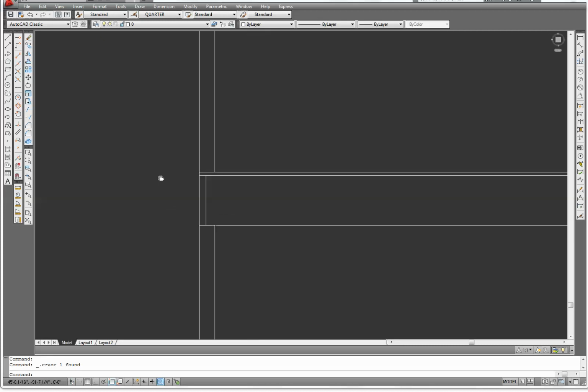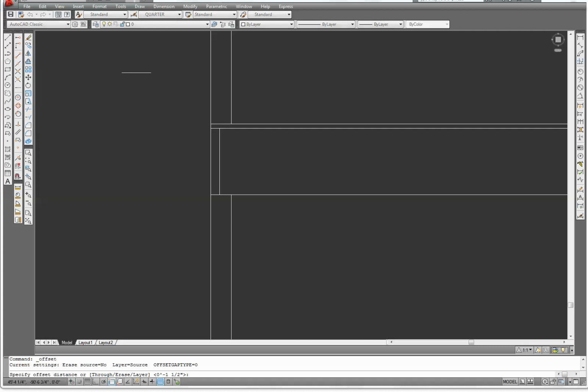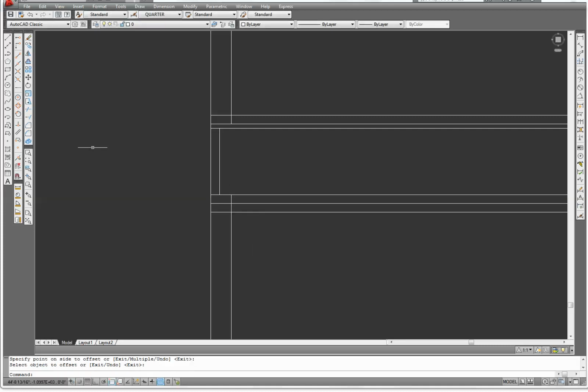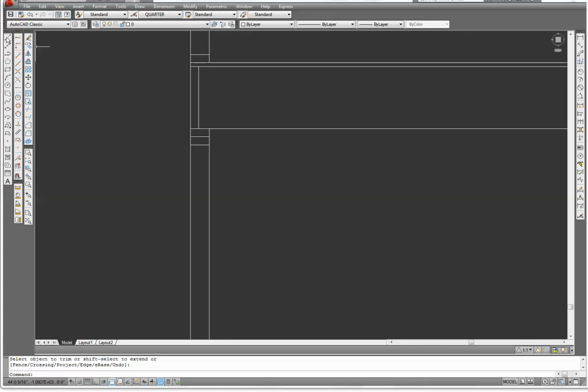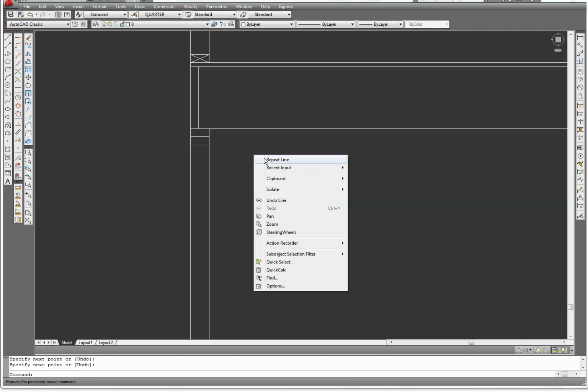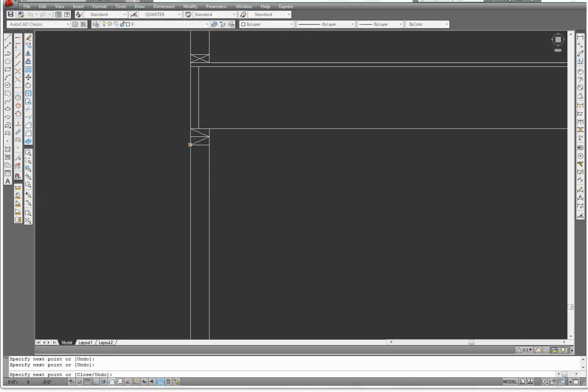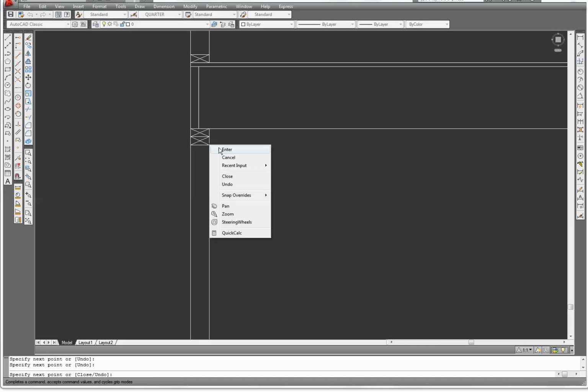Let's add the top and bottom plates. Offset, 1.5, enter. Trim, enter. Now we're going to add some diagonal lines, which in drafting indicates that this is an end cut of the board. So you're looking through a cross section of these 2x4 top and bottom plates.